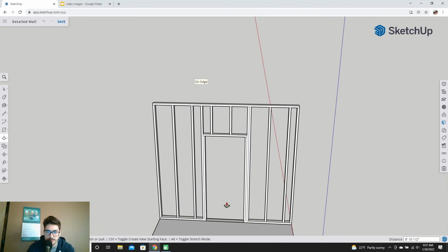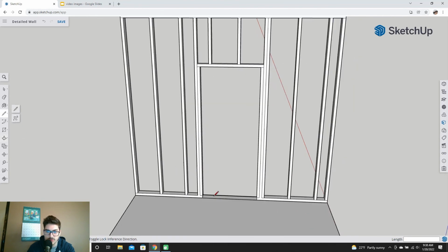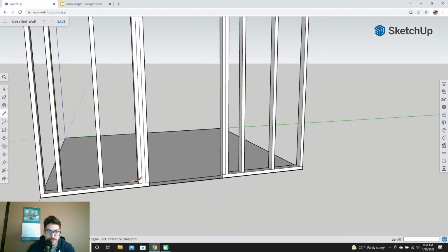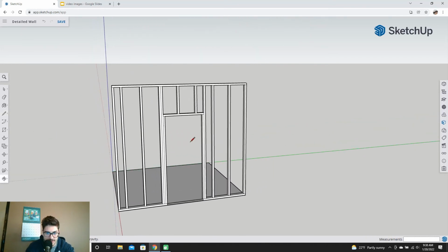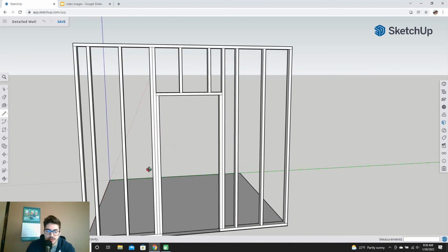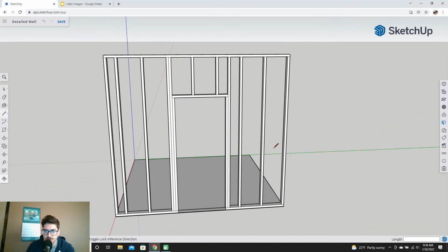And you're going to make sure that this is screwed laterally into your jack stud a few places too, because normally for these studs you're just putting them in the ground and then you're putting them in the ceiling. There's also, if you have a room that's above standard height, so say these were 10-foot or 12-foot ceilings, and if you don't want to worry about getting perfectly straight 2x4s, or you're worried about warping, you can put cross bracing in here.